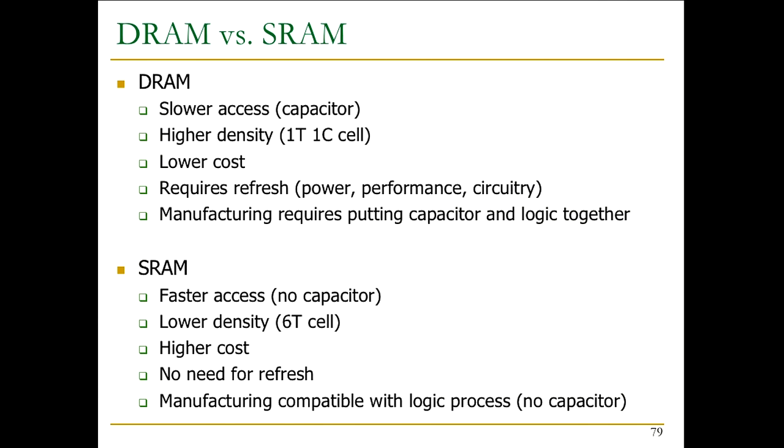In fact, when people want to scale to very, very low dimensions, they actually etch this capacitor in a three-dimensional way. So even though I draw it like this, it's really a three-dimensional capacitor, and the access transistor is on top of it. And for that three-dimensional capacitor, the aspect ratio is almost 1 to 90 today. So that's huge, you really drill into the silicon. It's crazy. And things are not as regular also.